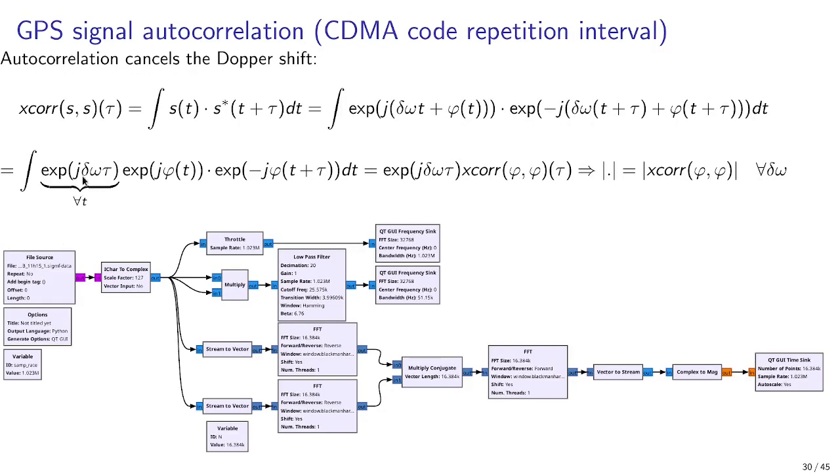If we now look at the expression of a cross-correlation of a time delayed code, we see that the autocorrelation, which is the signal multiplied by the time delayed copy of the signal, as the signal is plagued by the 2π Δf t, the frequency offset between the emitting frequency and the down-converted frequency, we do have this frequency offset.